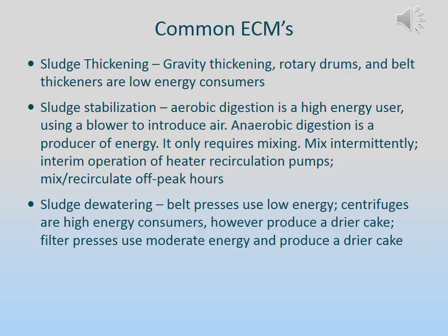Sludge stabilization. If using aerobic digestion, it is usually a high energy user. As mentioned earlier, an option is to consider on and off cycles for the air system. This option will also improve the process by reducing the nitrate concentration in the decant liquid.